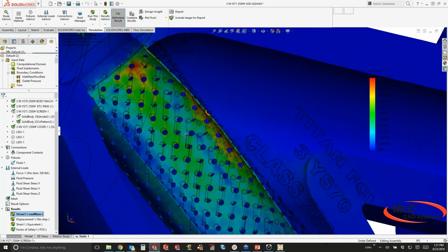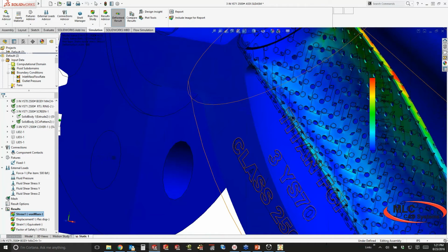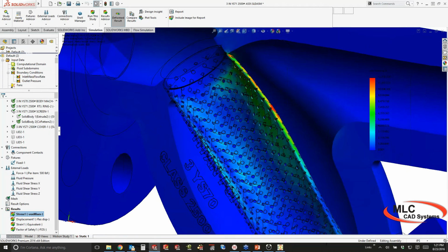And so we can understand and take a look at what value we have on the stress in that strainer, and we can start to size and maybe try to understand the life expectancy of that strainer given things like the erosion rate, the stresses. We can run a fatigue study from this result to understand, based on pressure spikes or pressure loading in the system, what kind of a lifetime we can expect, or life expectancy, on this filter on this screen.